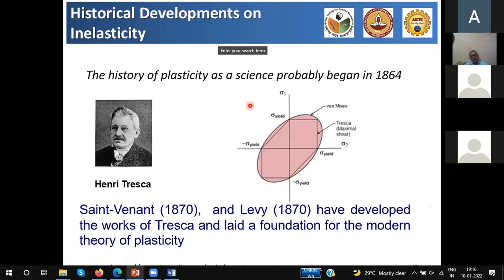And of course, later you can come up with a displacement or strain-based failure criterion, and a combination of stress and strain, which results in an energy-based failure criterion. All this failure, when you say failure in these cases, they all mean yield. They all tested things on metals, and whatever is called yield in metals is called failure. But it's a different matter that this Tresca failure criterion is still being used in brittle materials like concrete even today.